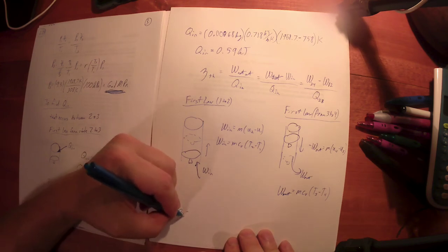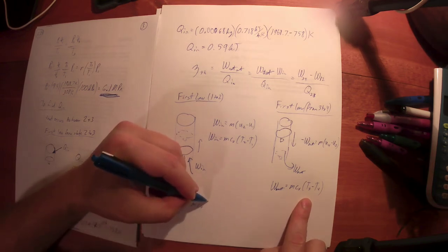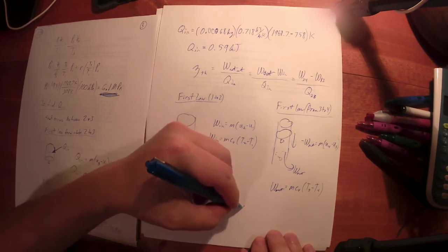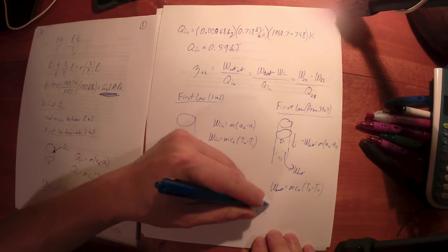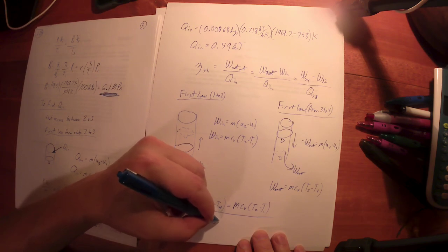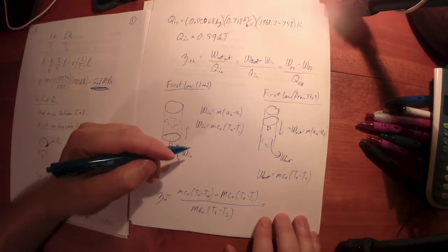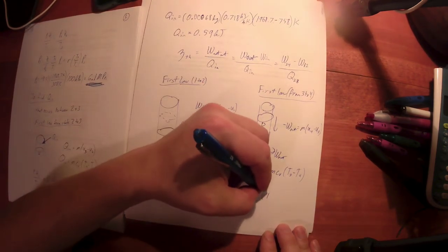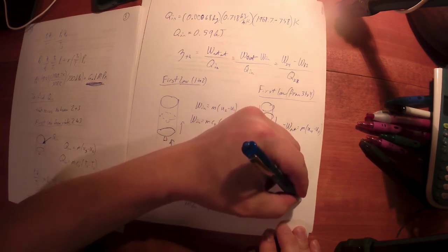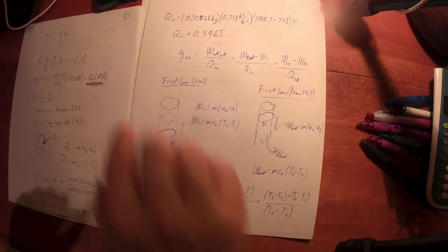So what happens here is this thermal efficiency. Right? Here this is m c sub v (T3 minus T4) minus m c sub v (T2 minus T1). The work out minus the work in divided by the heat in. That's m c sub v (T3 minus T2). And notice the mass and the specific heat go away. This is (T3 minus T4) minus (T2 minus T1), divided by (T3 minus T2). We'll come back and do it the easy way and finish it.